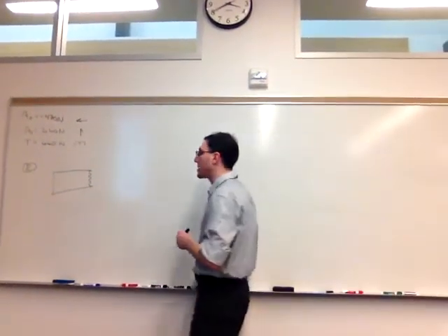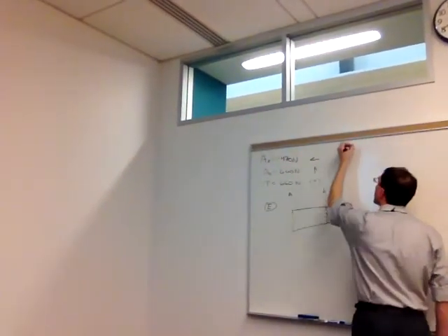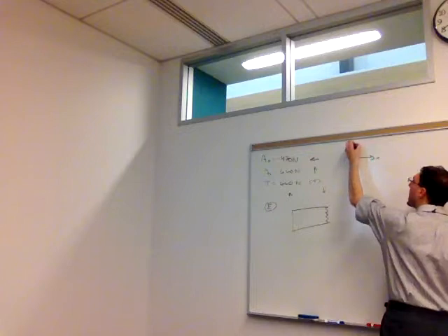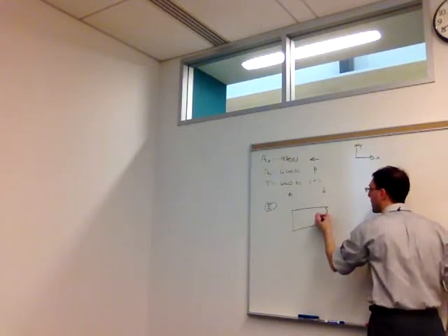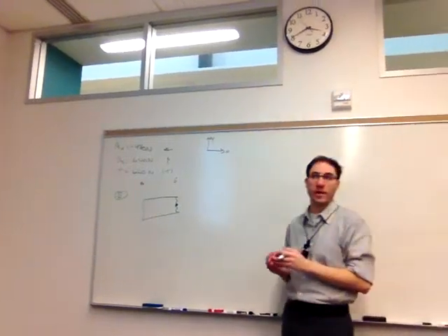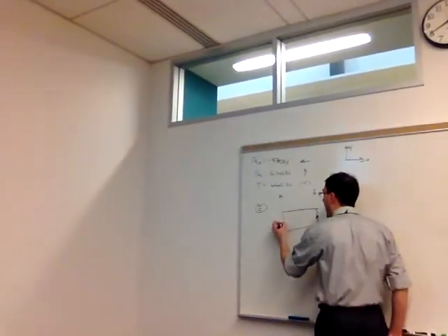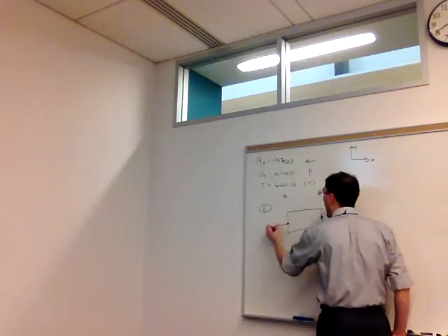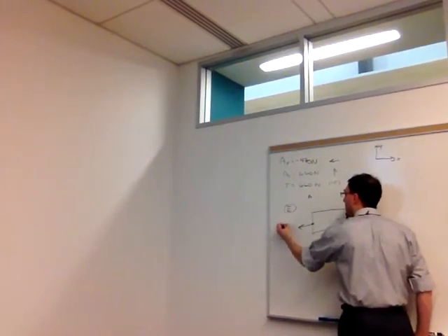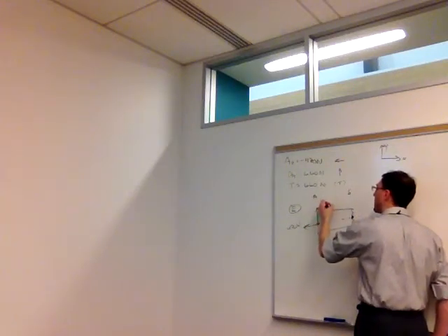So I'm going to copy exactly everything that was happening from A to E externally, and then where I made the cut, I have to model what were the loads keeping the material held together at point E. From the external picture, we know that at A, there was a pin reaction we discovered to the left of 470 newtons and vertically of 660 newtons.